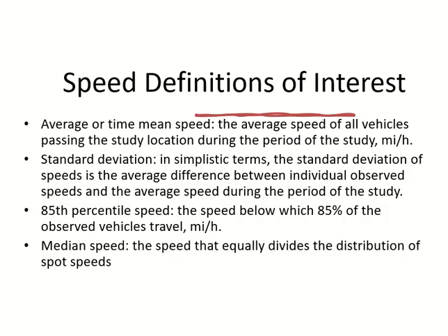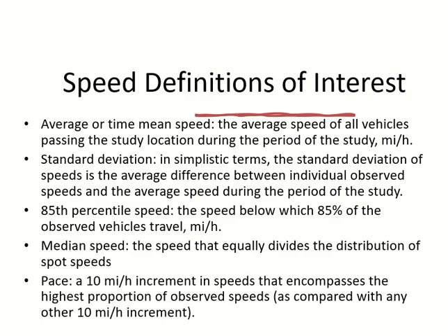Okay, median, you know, right? Median, the middle value, exact middle. You will have like 50% value here, 50% value there, exact middle. Then you have the pace. So pace is not a value, it's a 10 mile per hour range. Which 10 mile per hour range? The range in which the percentage of drivers are more than any other equal range.